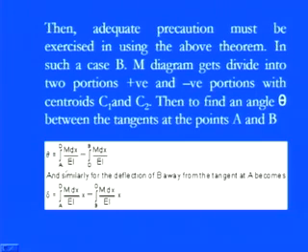So for that we have A to O M dx by EI, and then from O to B, where you see the abrupt change was there, the hogging part is there. So for that, O to B M dx by EI, and then again the same procedure which we need to follow for the deflection part, that once we have the slope, we can go for a similar way,